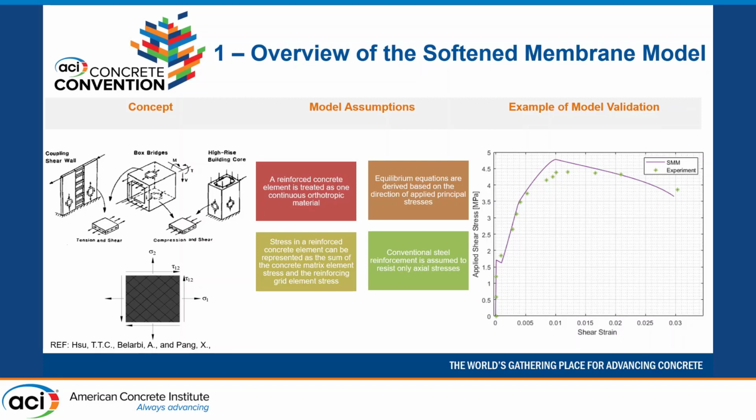And the idea behind the panel tester is that you can characterize an element behavior and treat the heterogeneous material as something that's continuous. And so that's the potential behind this model, that it allows you to characterize a structural behavior by characterizing an element of that structure subjected to any stress state, and using that in finite element frameworks to be able to assess the structural behavior.